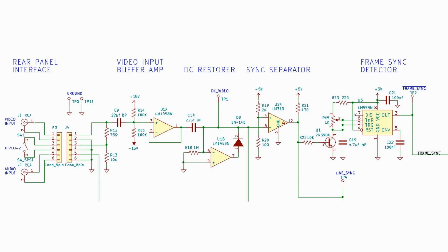During the time when the sync pulse is missing, it's now 2 lines long between sync pulses, and the capacitor has time to charge up to above the threshold voltage of pin 6 and triggers the 555, which then outputs a low-going pulse, which I call frame sync not. And this happens once per frame, and frame sync not is sent to the frame scan circuit.